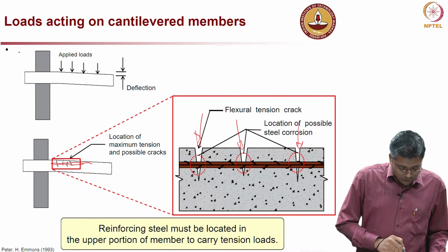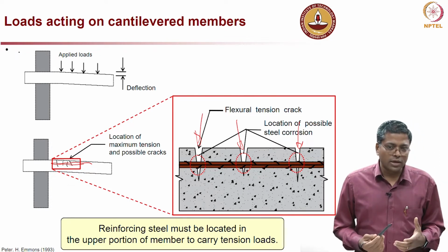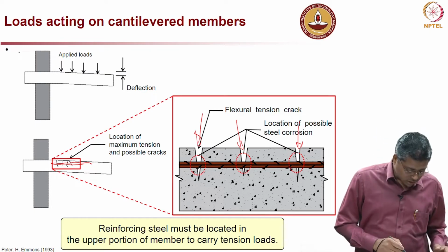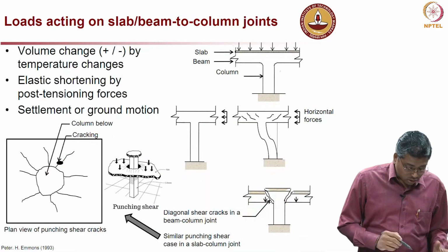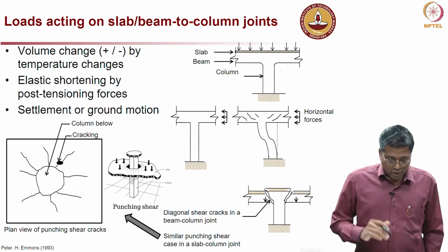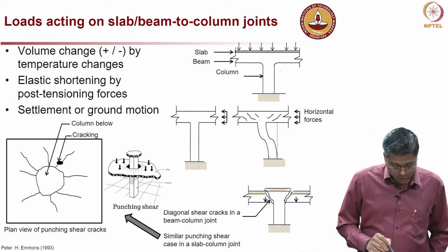Anyway, the point is, steel is good for tension, or it is meant for taking tension. So, wherever tensile loads are acting, that is where you have to provide steel, and not in other places. Unless load reversal is considered, that is a different story.